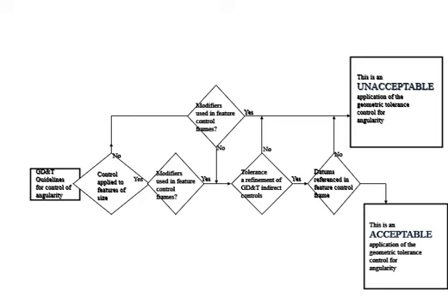So I'm going to go ahead and draw that for you. You're dealing with it like this, okay? So control frame, we want the angularity. So we always look at, number 1, your tolerance. I'm going to just write T right here, where the tolerance value is. I'm going to draw it like this, because I drew it really big. So you have your tolerance value here, and sometimes you're going to see an M or not, in the material condition, which usually has a circle like that, and then of course your datum. And that's the order of what we're doing.